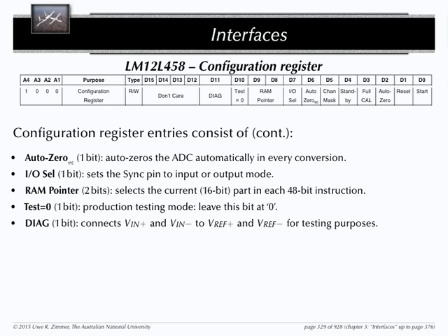You can set an auto-zero in the configuration register, which means that you have an automatic calibration before every conversion if you want to be a bit more precise. If you want to convert 12 bits, you better be a little bit careful that your AD converter is nicely calibrated. You define what synchronization mode is used on the I/O pins. You define which is my current instruction.